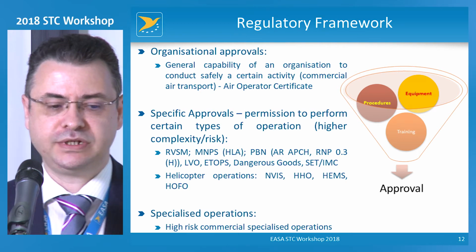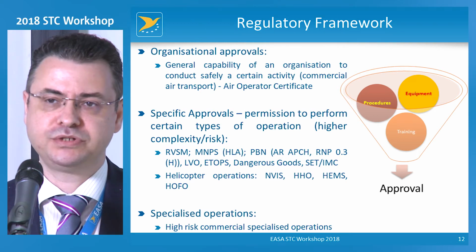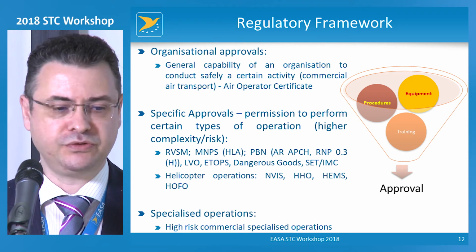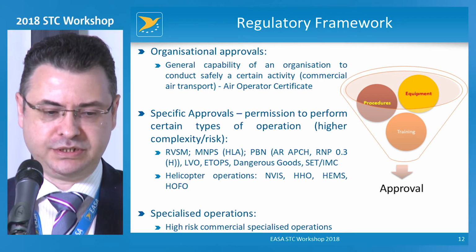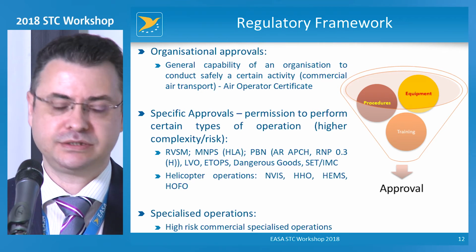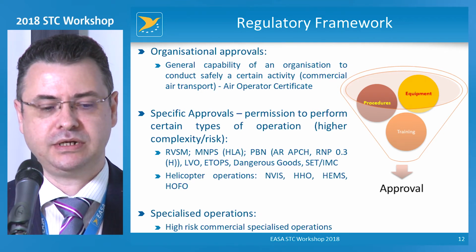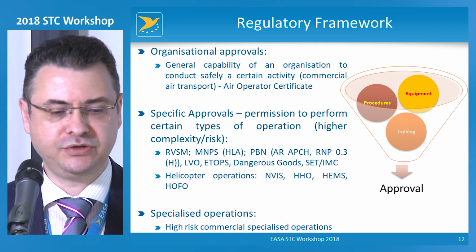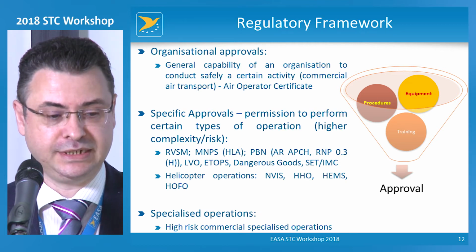In the case of the so-called RNP approaches with authorization required, so very complex approaches, mostly 3D. And one other specific approval is the operations with 0.3 accuracy conducted by helicopters.